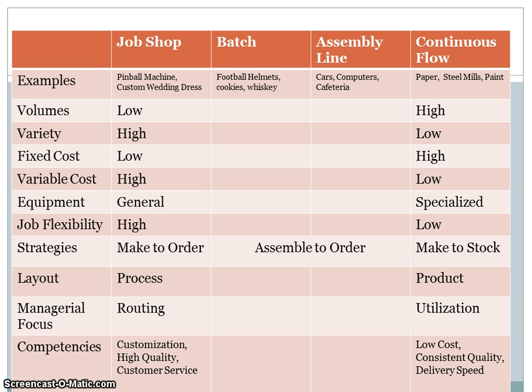Whereas in continuous flow and assembly lines, because the assembly line is already laid out for you, there really doesn't need to be any scheduling. The only area that you need to schedule is the first station on an assembly line, because every single station after that does product in the same exact order. So what they try to do is focus on getting and keeping very high utilization. So they focus on stuff like assembly line balancing to make sure every worker is utilized, say, at 90 or 95%.